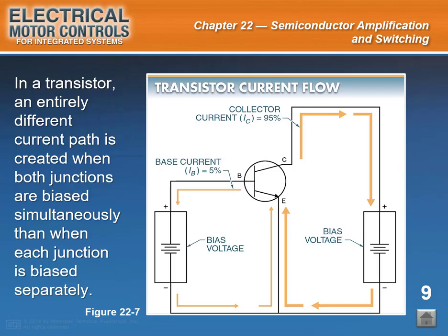The base collector, or BC junction, is reverse biased to prevent current flow unless multiplied current carriers proportional to the input signal are injected through the thin base region and into the collector, where the reverse bias BC junction voltage completes the path back to the power supply. So, even a little emitter to base stimulus current becomes a gain multiplied emitter to collector current through the amplifier or switching circuit. Emitter collector current is the sum of emitter base current and base collector current.